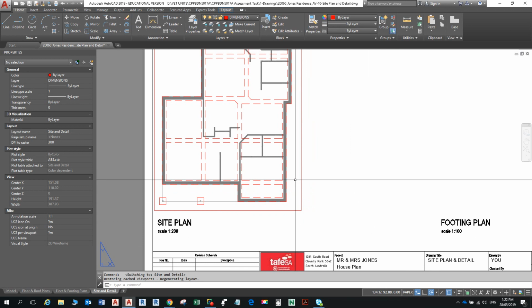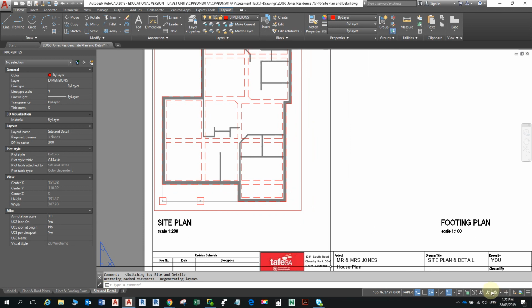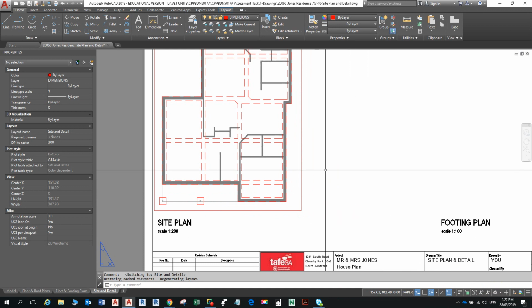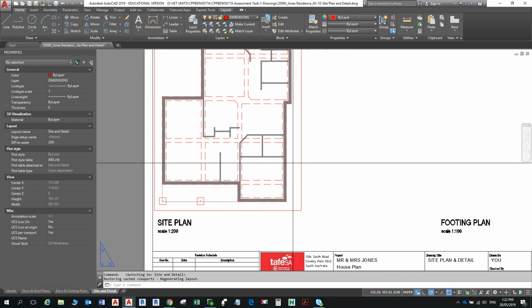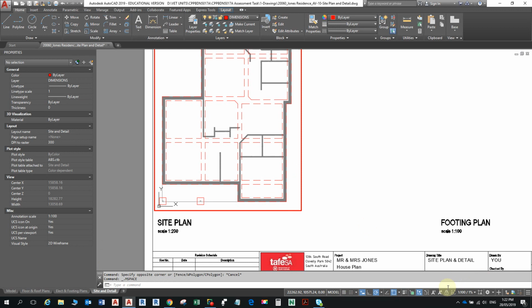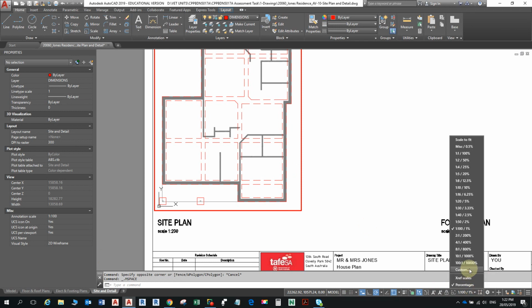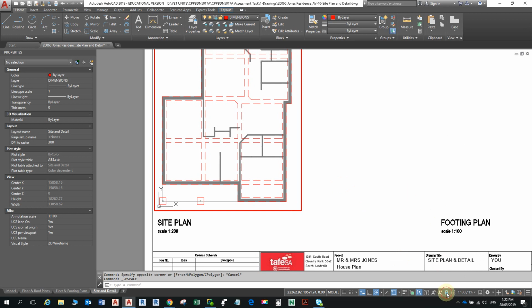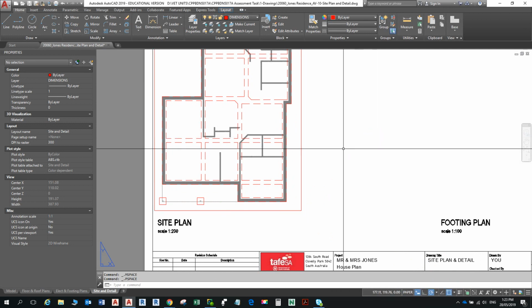So what you need to do, because you can only do those in model space or through the viewport, is double click into a viewport, and then that scale portion of the status bar will appear. Just click down there, and then, sorry. Oh, well, you have to unlock your viewport. Oh, let me just check. All right, so yeah, some of you can't do this.